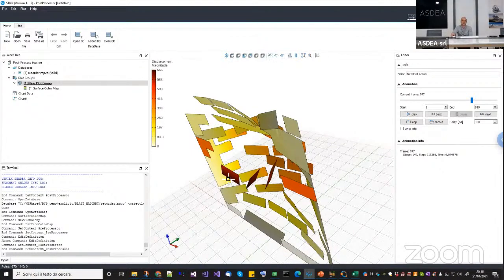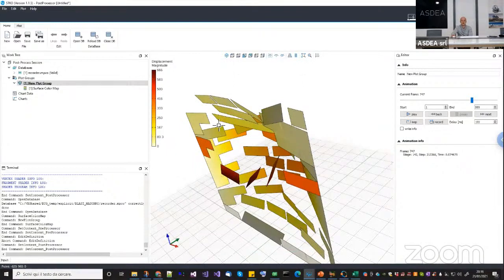So for example, if you do this model here and you remove the mass from the rotational degrees of freedom, it will be singular. Okay? So you don't have to ensure it yourself, you just make sure that the user assigns masses everywhere. If it is not like that, OpenSees will issue an error. It will say the diagonal at index 10 is equal to 0, so I cannot invert. There is no need for you to check. OpenSees will stop by itself.